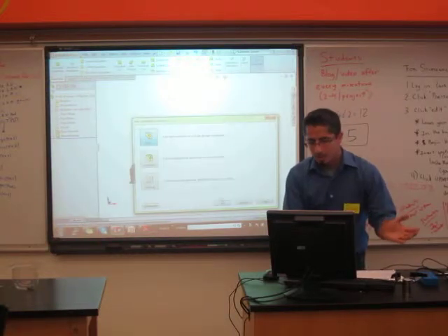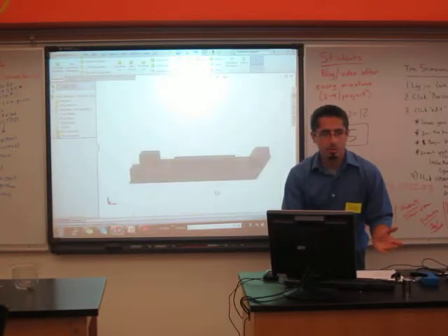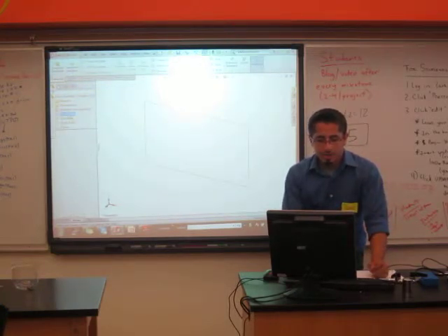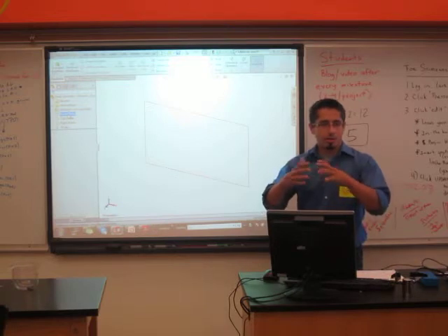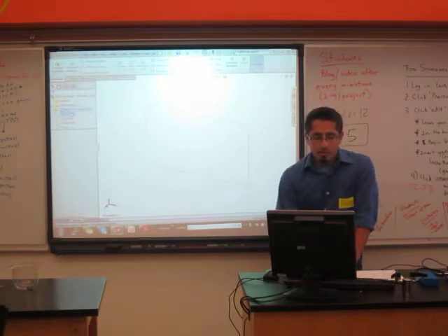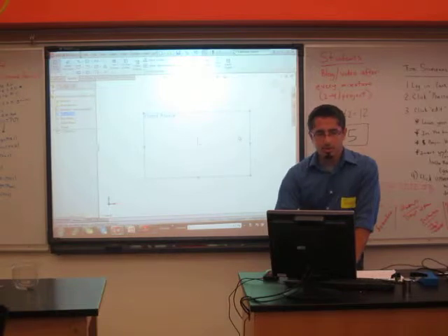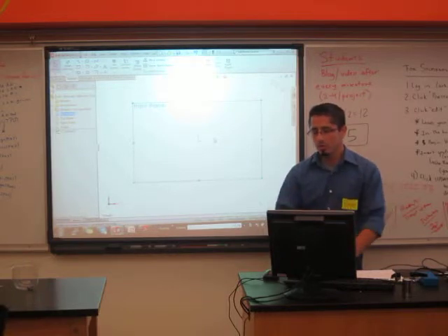All the CAD software is very similar in terms of what they do. You draw parts. For instance, I have these planes here. Everything's in X, Y, Z, and it's always in 3D. When you draw, you usually draw in 2D. So I'm going to pick the front plane, and I'm going to start a sketch. I want to draw on this plane. In SketchUp, all these things are very similar. SketchUp's a little easier to use. This takes a little more input, but the more input means you have more control and more accuracy.